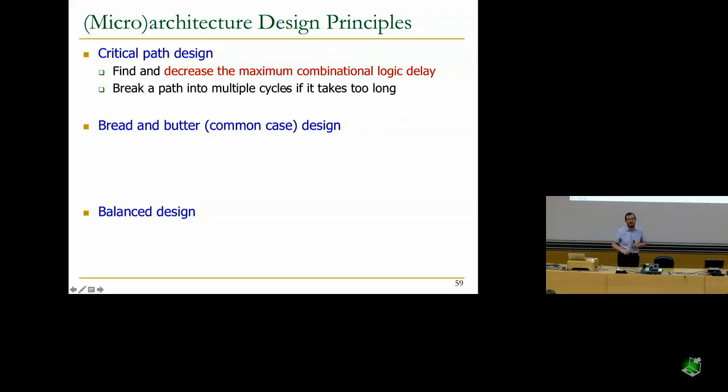So clearly we don't have this option in the single cycle microarchitecture, right? Single cycle microarchitecture gives you very limited freedom to minimize your maximum combinational logic delays, because that's really dictated by the longest time it takes to execute the worst case latency instruction. You can reduce that a little bit perhaps, but it's really long to begin with. You cannot say, oh, this is my clock cycle time, and I'm going to make sure every instruction executes correctly given this clock cycle time.